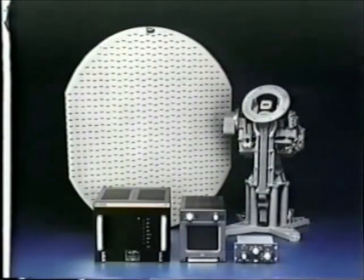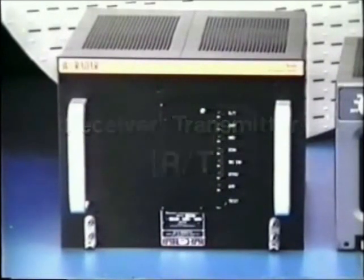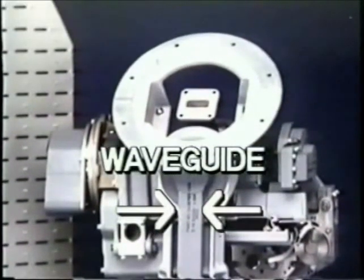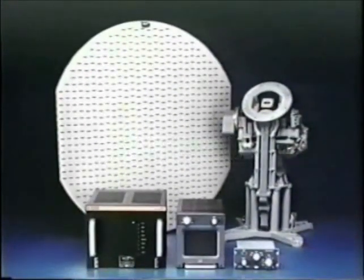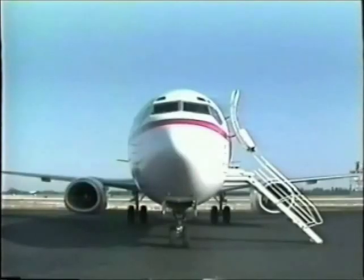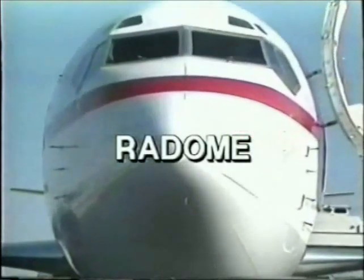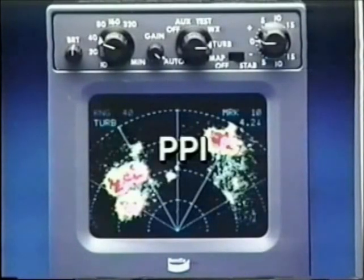The Bendix Arinc 700 Series Airborne Weather Radar installations contain 5 basic components: a receiver-transmitter unit for transmitting, receiving, and processing the radar energy; a waveguide which guides the microwave energy back and forth between the antenna and the receiver-transmitter; an antenna which focuses the microwave energy into a beam and continually scans it from side to side, and has the ability to point it at a specific elevation angle; a radome, which is a protective covering for the antenna that allows the pulses of microwave energy to pass through; and a display unit, which displays the processed radar echoes as well as provides a mounting point for the system's controls.